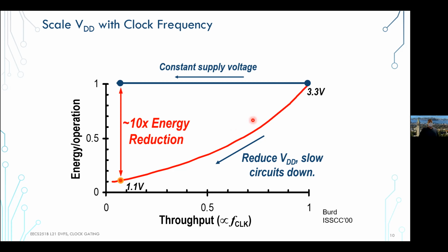So what you normally have is a voltage margin that people add and say, look, I'll only be able to get, let's say, up to here. And at that point, it's 60% of energy per operation versus the optimal of 50%. So I'm paying a penalty of, let's say, 20%, but that's my buffer margin.